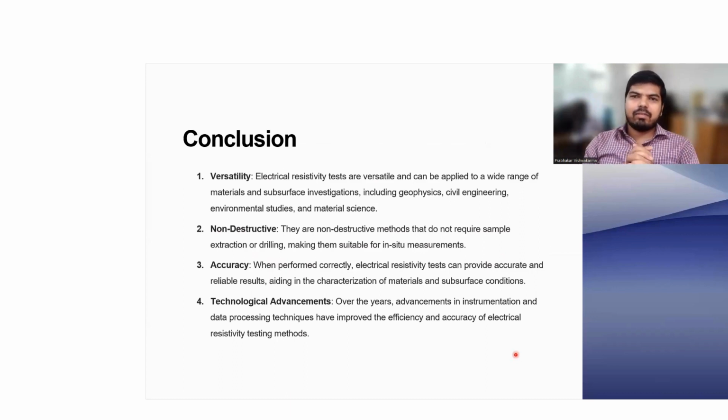Electrical resistivity tests are versatile and can be applied to a wide range of materials and subsurface investigations, including geophysics, civil engineering, especially geotechnical engineering, environmental study, and material science. Non-destructive: these methods do not require collecting samples by drilling or extraction, so it is a kind of in situ measurement.